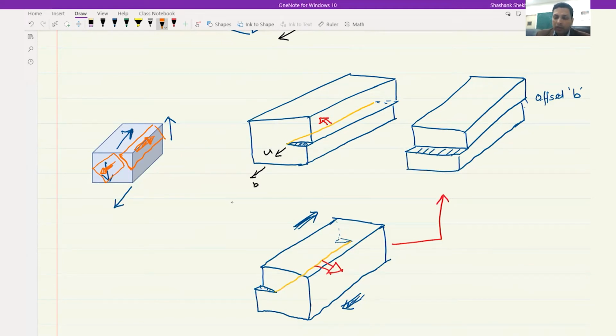But then this dislocation line is not uniquely confined to one glide plane. This particular dislocation line, if we just take Burgers vector and the line vector, it has several possibilities, and therefore it can also move along this plane. And in which case you would get a crack which would look very different, which may be something like this.